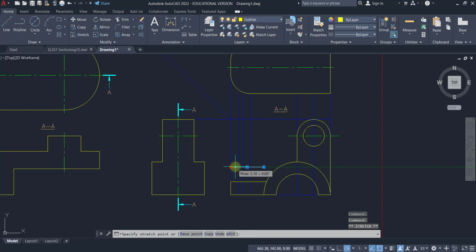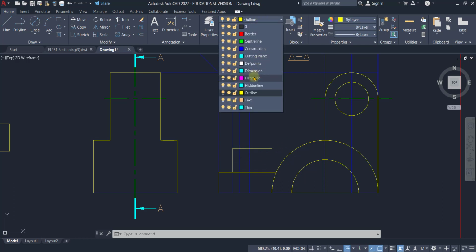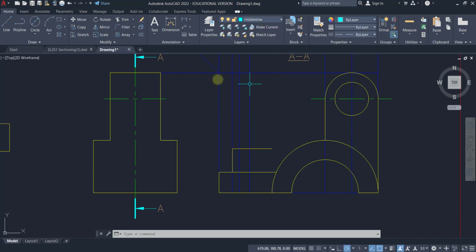Shorten it. So I know that this line is for the boss. Because it's going to be connected to a web, I do not know how much to cut off, so I leave it first. I go to the hidden line layer and draw my hole, the true hole.